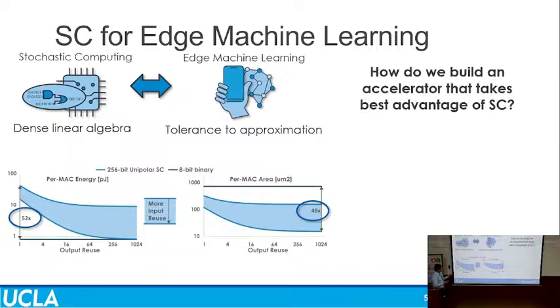One thing I want to emphasize is if I do 8-bit multiply addition or anything like that, the benefit in energy per se of the native operation is not very high with SC versus conventional arithmetic. Where the benefit is coming from is the size of that multiply accumulate unit is 50 to 100 times smaller. So I can pack many more of them in the same chip area. If I can pack many more of them, I can get much more input, output, and weight reuse.